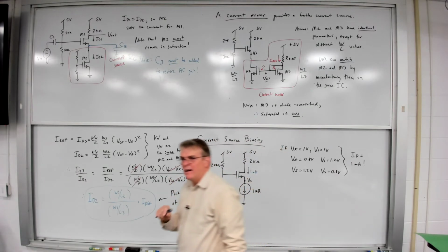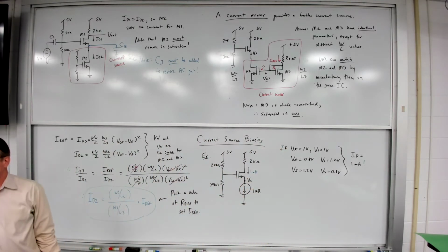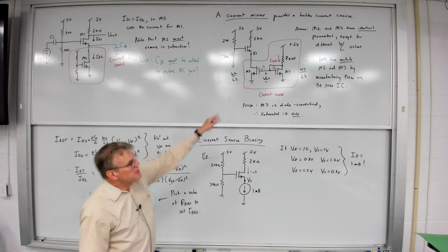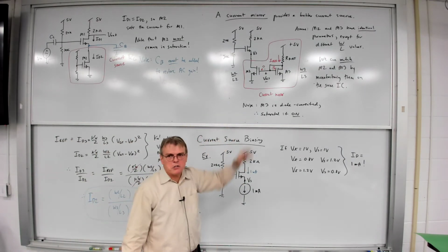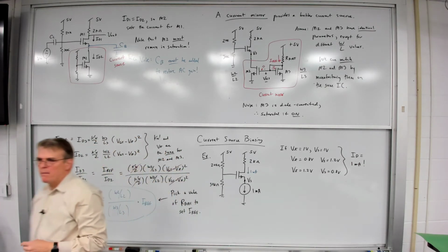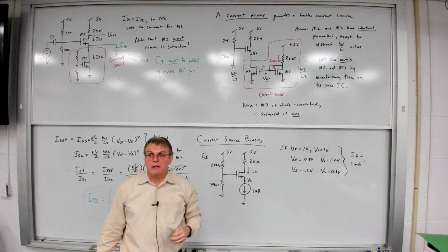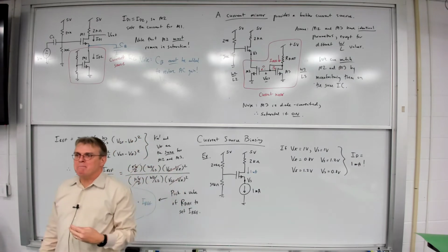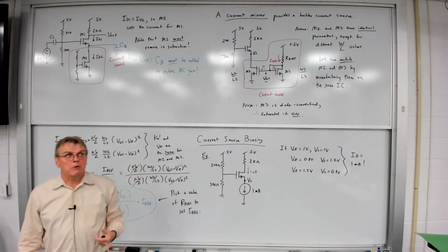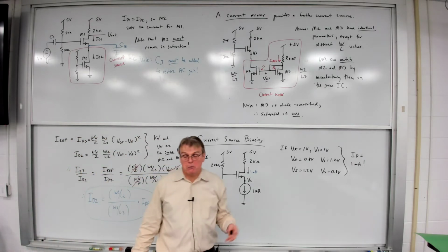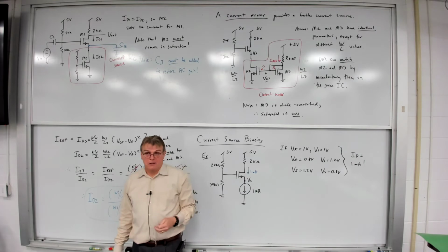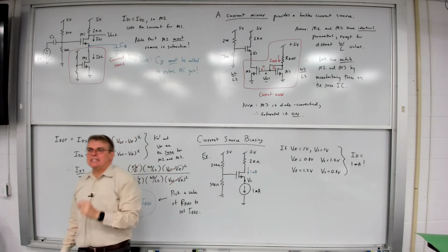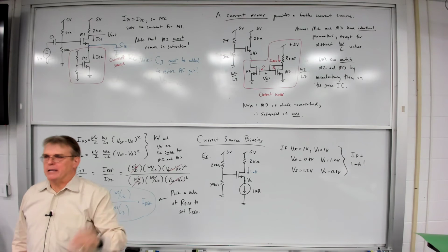So this is a much better way to set this bias current, because now, because of the matching, I can tolerate variations in those M2 and M3 transistors. Of course, I'm still having to deal with the resistor, the R bias, and it turns out there are even more sophisticated tricks people use in order to make the bias even less sensitive. For example, techniques like band gap references, which are, quite frankly, unfortunately, beyond the scope of this course. But in more advanced analog design courses, you can learn more tricks about how to make biasing even less sensitive and more stable over all operating conditions.